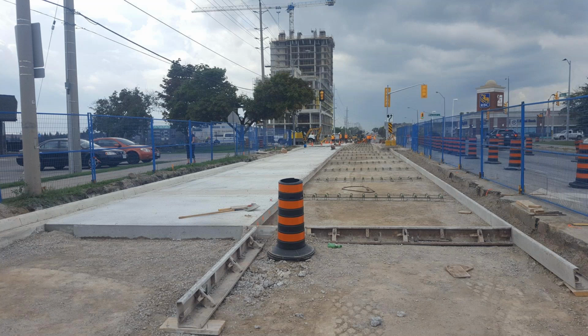So there's another section of how they staged. You can see they used these formworks, and they did one lane at a time. And then once the lane was cured, they used it as the formwork for the adjacent lane. We replaced some curbs as part of this project as well, just because the curb was old and needed to be replaced.